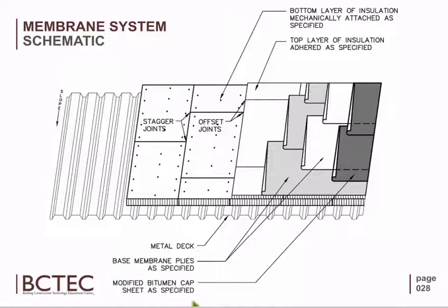Why is it like that? Well, a lot of times, if you're not experienced in what we call chasing a leak, you'll go inside, and if it's an enclosed ceiling, a drop ceiling, you can't really see where the leak's coming through. You've got an idea, so the typical contractor will pace it off, north, south, east, west, get their paces, and then they'll pace it off on the roof and just look in that general area.